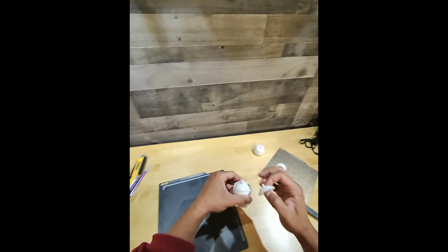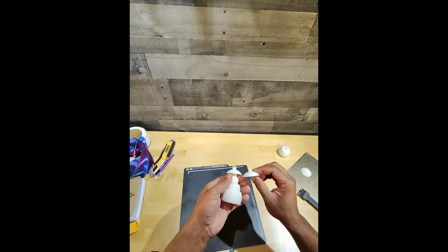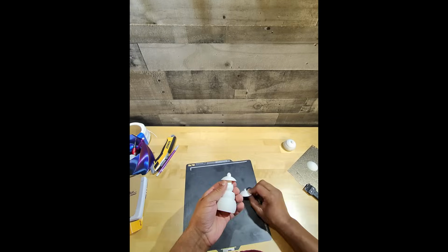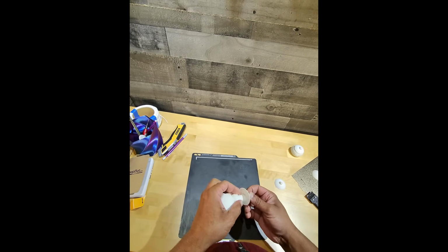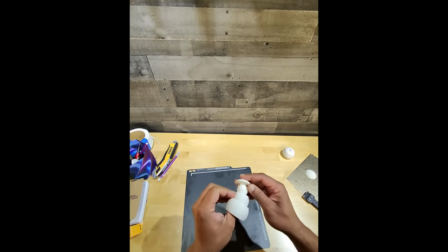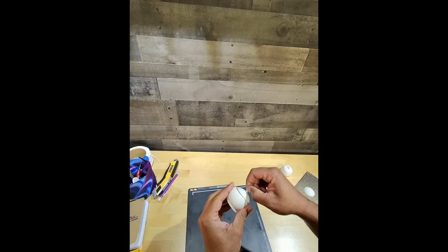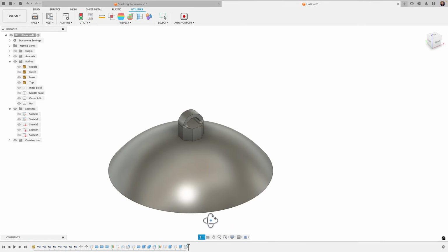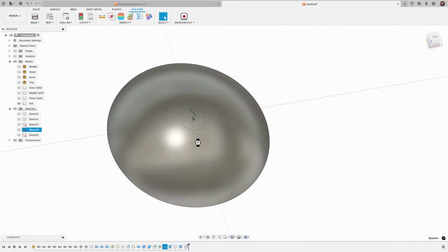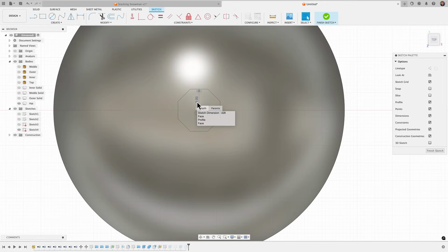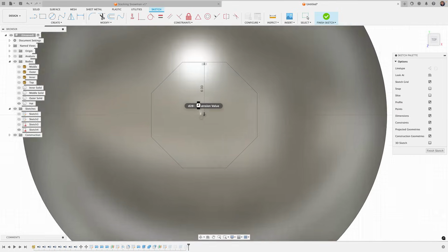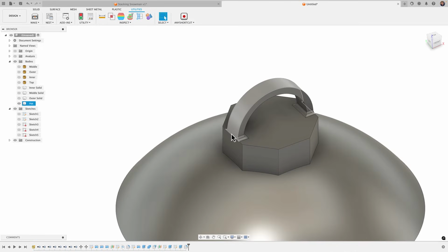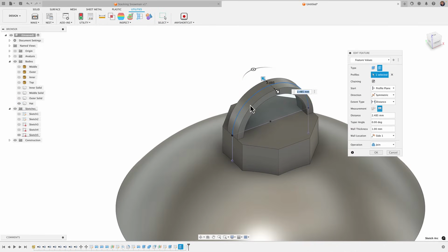Let's see, that's the other one. So why did I make it so small? All right, let's check the fit. Fits good, it's just tiny. Okay, let's fix that. All right, back in Fusion, let's go back into that sketch here, and I'm going to change this from 3 to 6. Finish sketch. That'll make it bigger, and then just this extrusion here we have to fix.